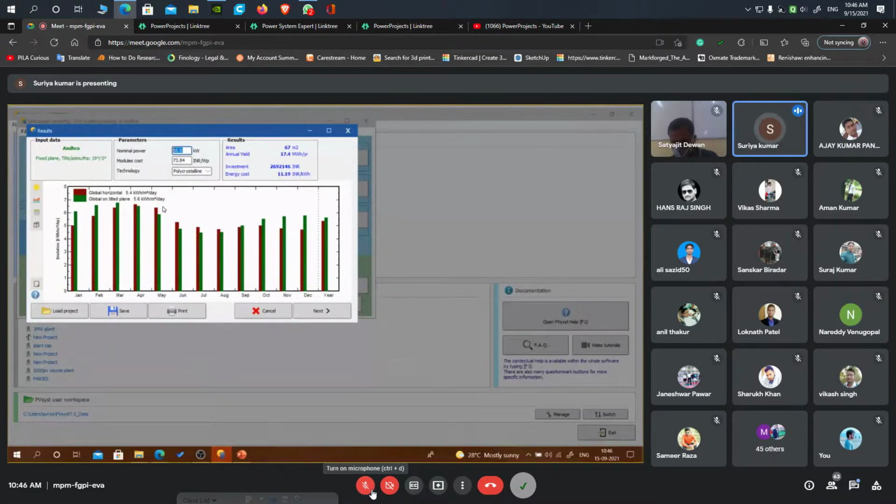We have tilted it, 19 degrees. Why have we tilted? Because this is the reason. You can see, by tilting your panel you are able to generate somewhat more power compared to horizontal. This is where the tilt angle comes into the picture. This is why, in whatever solar plant they are building, they tilt the panel to some degree. That is the thing you need to observe here.